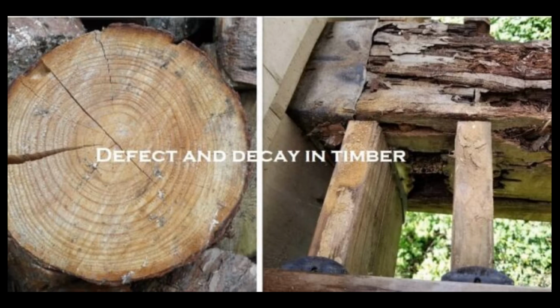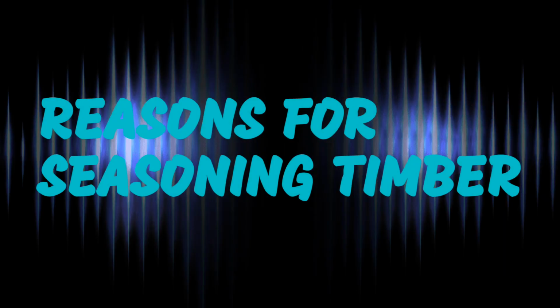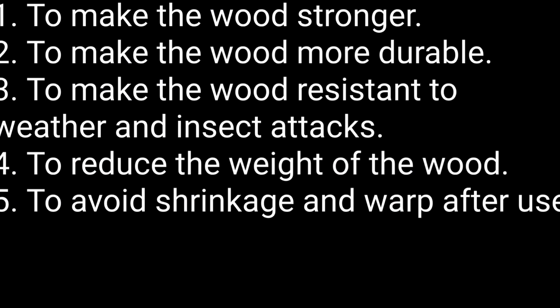Green wood, that is fresh wood, is prone to decay, warp, or even bend when it dries. Hence, there is the need for seasoning the timber before construction. What are the reasons why timber should be seasoned? 1. To make the wood stronger. 2. To make the wood more durable. 3. To make the wood resistant to weather and insect attacks. 4. To reduce the weight of the wood.